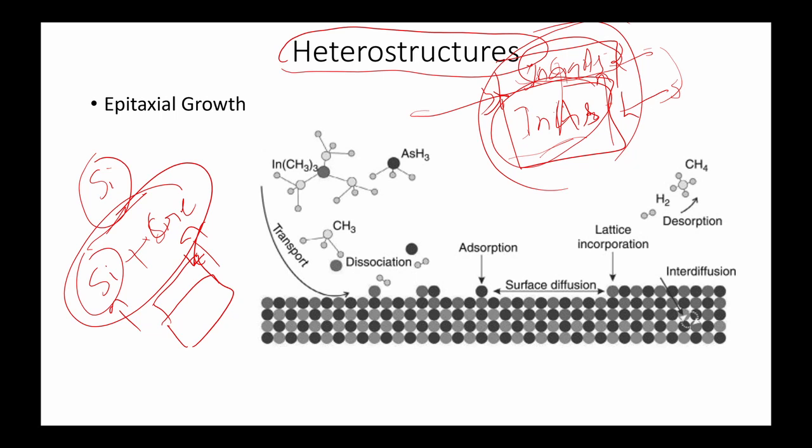Okay, it will be cracked because germanium has a larger size, so the lattice parameter of germanium, A of Ge, will be more than A of Si. So growing over that, in the next slide I will show you why it is important, because the interface will be more strained. That will be cracked, which we do not want.